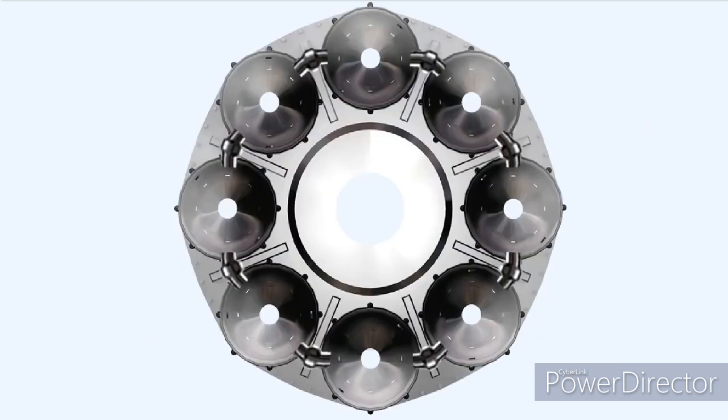Immediately after light-up, the flame in the combustion chambers which have the igniters causes an increase in the pressure within those chambers. The pressure differential between a chamber which has a flame in it and those adjoining it which have no flames drives the burning gases through the interconnector pipework. When the burning gases come into contact with any unlit mixture in the adjacent combustion chamber, they ignite that mixture.